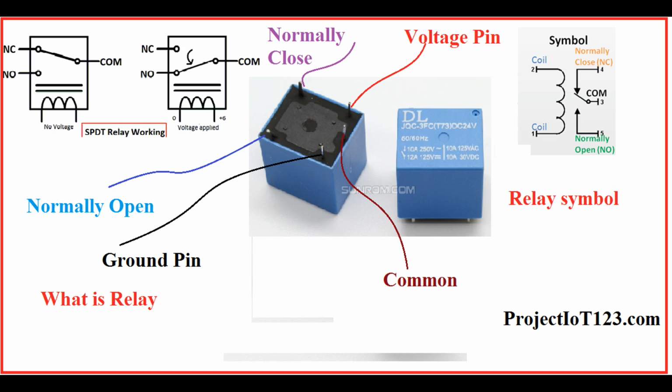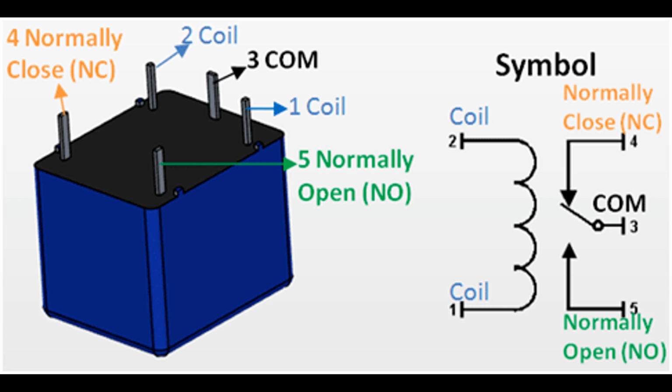Timers and sequencers. Timers, counters, and sequencers can generate timed or sequential input signals to control relay operations in a predefined manner. For instance, a timer may send a signal to activate a relay for a specific duration, while a sequencer may coordinate the activation of multiple relays in a predetermined sequence.